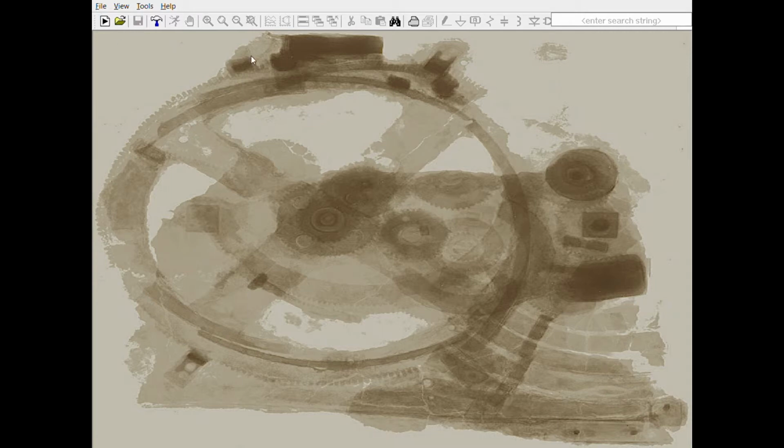First step, we have to open up the software to run the circuit. We will use LTspice and click on new schematic, and by referring to the lab sheet, we need to pick the component which is a diode.